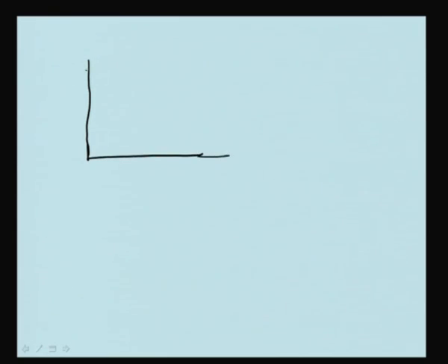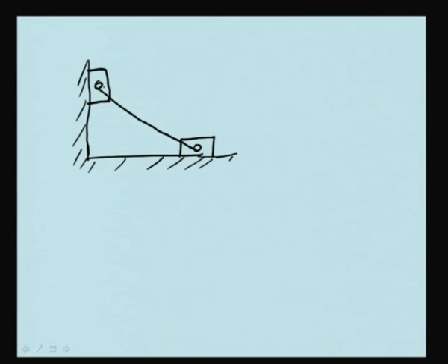Now, if you are having a mechanism like this, there is a slider here, there is a slider here, join this by pin joint with a link, this one. So, this slider is A and this is B, A can slide on the horizontal floor and B slides on the another, this perpendicular. Okay. Now in this case, if you have rod AB joined by pin, you are required to find out the angular velocity of the rod AB.